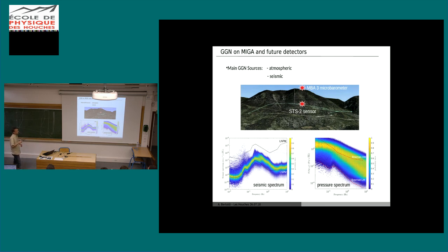And we also studied seismic noise, because there is a well-developed network of seismometers on site there. This is what we measured in, I don't remember, I think it was a 4 or 5 day campaign. The seismic spectrum is rather close to the low Peterson noise model, except in the frequency band around 1 Hertz,